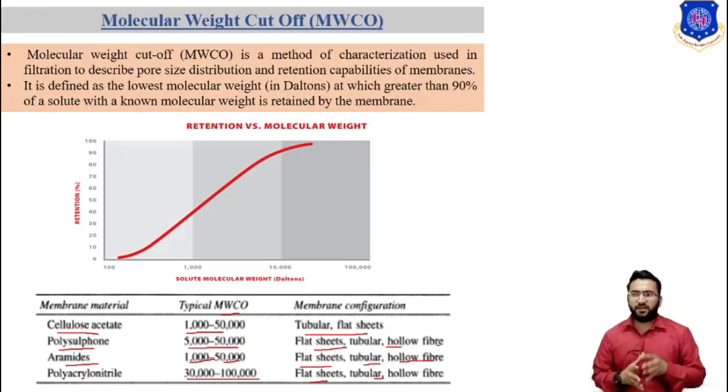The concentration depends on the condition under which the filtration measurement was performed. Also, specific and non-specific adsorption of solute to the membrane surface can occur, and overestimation of percentage of rejection.